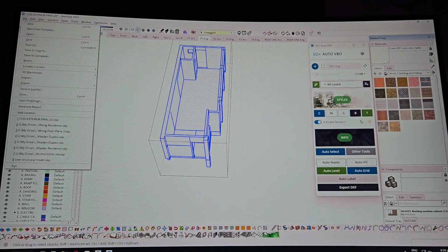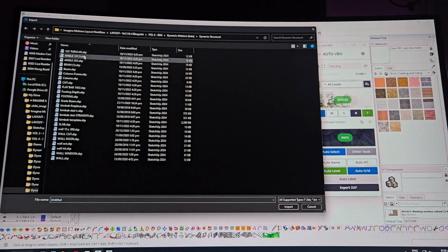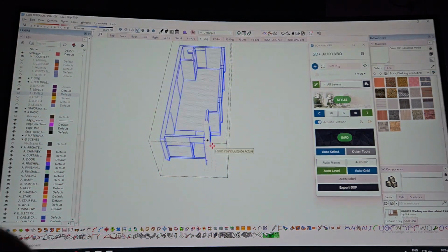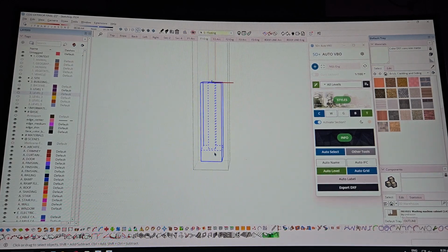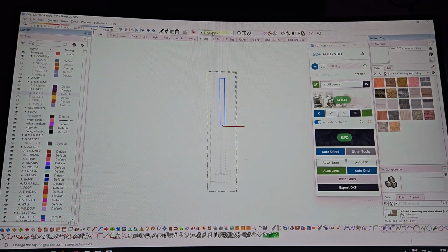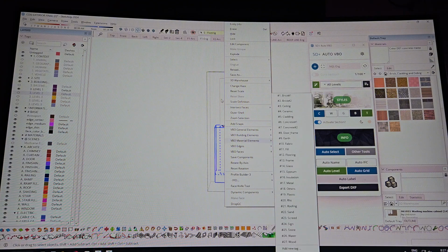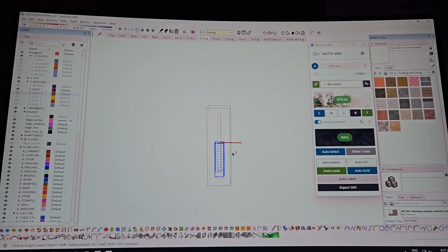While I'm at it, maybe we could insert or import my dynamic structural. Let's try the column frame. Let's check this column frame first. I experimented on this one years back. Column frame comes with the footing column, and then the column. So it already has its own tags, which is similar to VBO but not exactly the same. So we can actually transfer them to VBO's tag system. But since this has the word column, this has the word footing, I think we will do just fine.